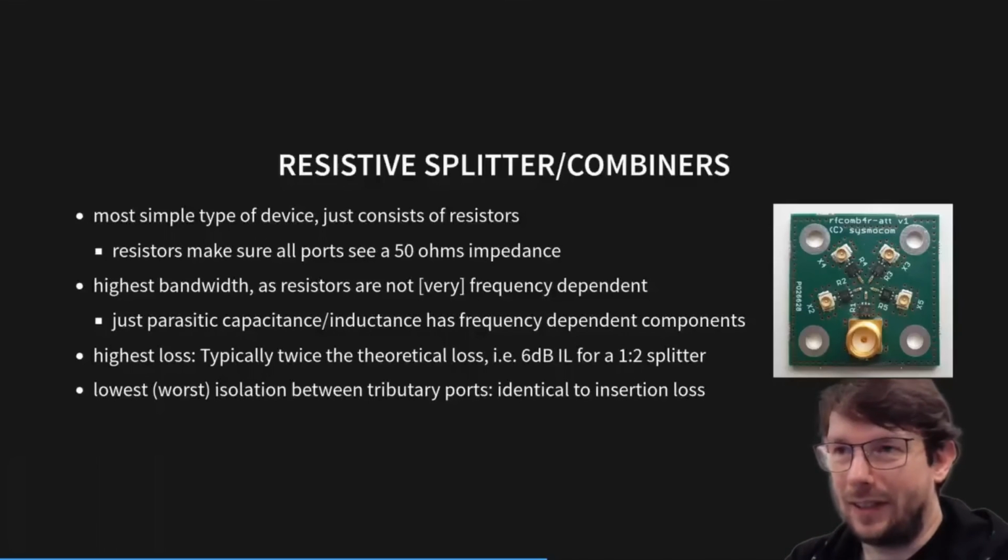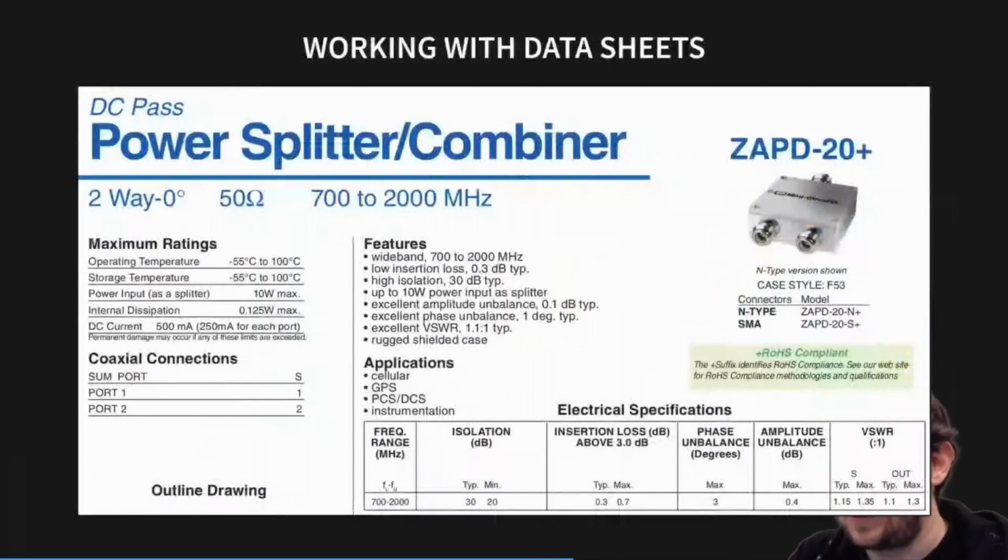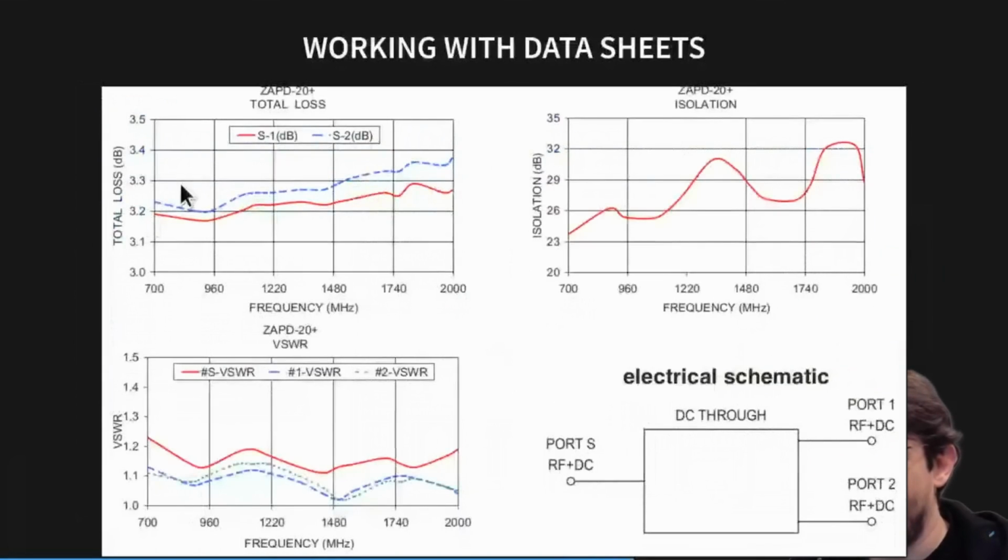That's basically a device that you can attach any kind of RF distribution network to, and it will plot you the attenuation, not just, but as a minimum, it will plot you the attenuation over the frequency. So basically, the kind of plot that you saw here with loss over frequency, that is something you can generate automatically on the screen with the network analyzer, and not just for a single device, but for your entire network.